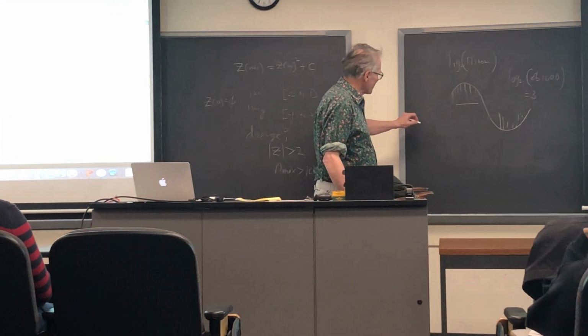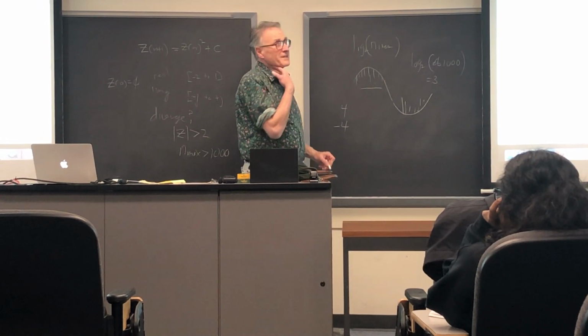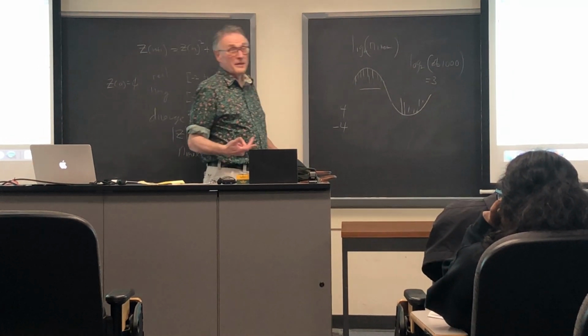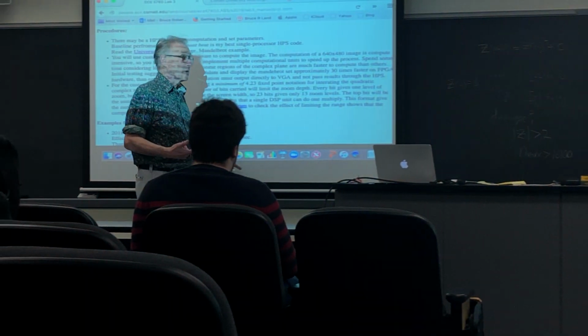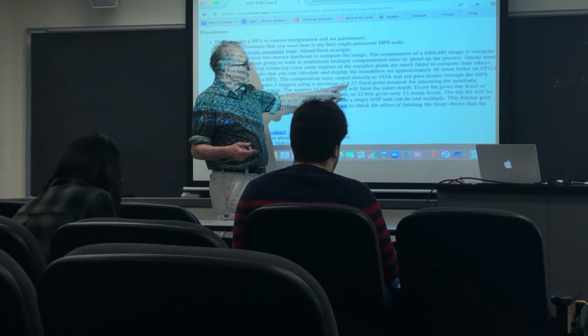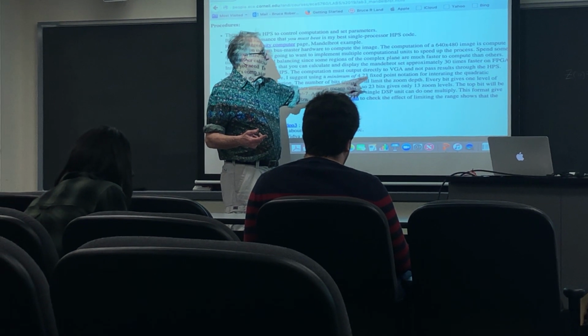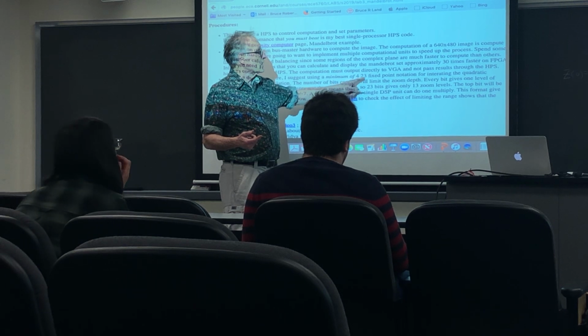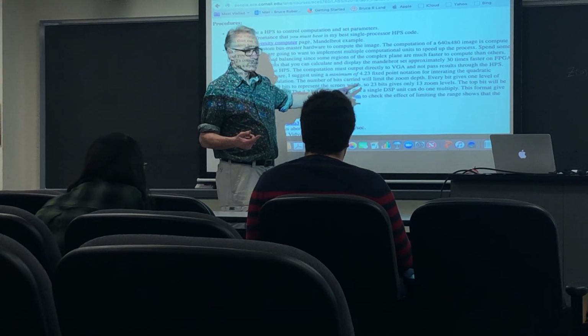So you have to be able to represent 4 and minus 4, and it's not a bad idea to have an extra bit in there in case you overflow. So 4.23 allows you to have a range of plus minus 7 while fitting the whole calculation into one 27-bit multiplier.